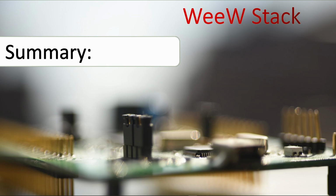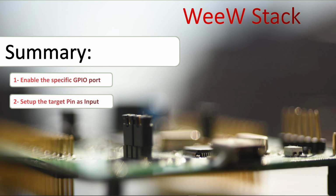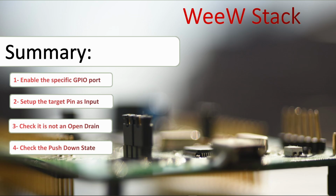So to finalize and have a final conclusion, first of all, to have an input you need to enable your specific GPIO port. After that, you have to set up your target pin as an input within the GPIO itself. Then you check that it is not an open drain. Finally, you check the pull-down state if you are using a high voltage as your reference.